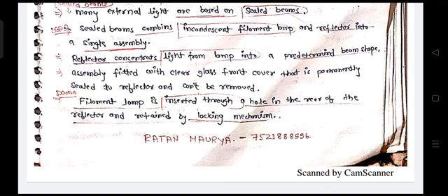And lastly, the filament lamp is inserted through a hole in the rear of the reflector and retained by a locking mechanism. Also with this I am mentioning one more thing: you should not touch a strobe light with bare hand, because in your hand there may be moisture or oil, which if it accumulates on the surface of the strobe light, will crack that surface, because it is a very high temperature surface and heat will be accumulated with that oil and water from your hand. If heat is accumulated in those areas, it will break that glass, and that will damage the light. So never touch a strobe light with your bare hand. That's all about it.